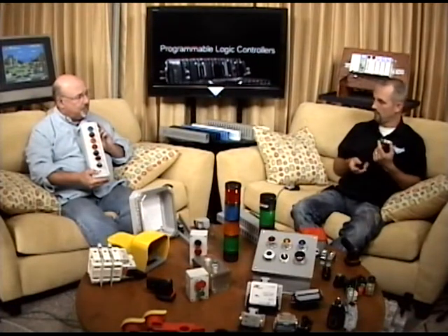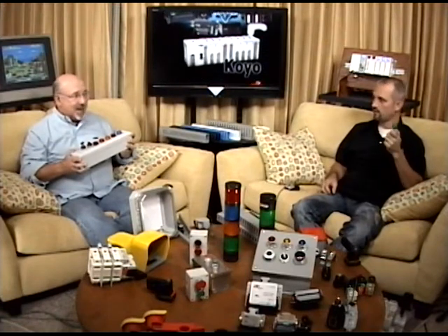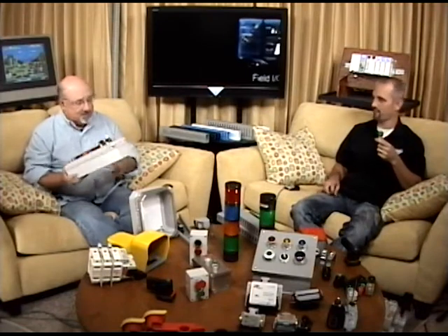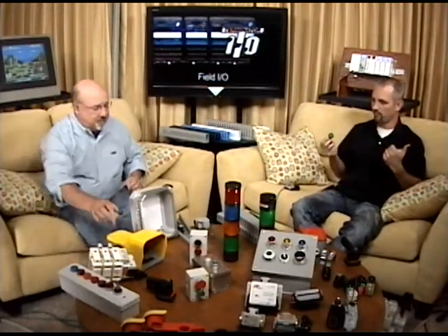We offer the incandescent and LEDs. Now let me push you to get the LEDs. If it's $1 more, buy the LED. If it's $10 more, buy the LED. Save yourself the hassle, because anytime you use anything in an industrial environment, there's going to be vibration and whatnot. And you know what an incandescent light is going to do. It's going to give out after a while, from vibration, heat, temperature. The LEDs are definitely the way to go.